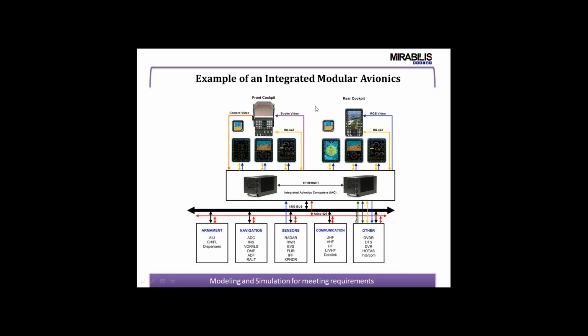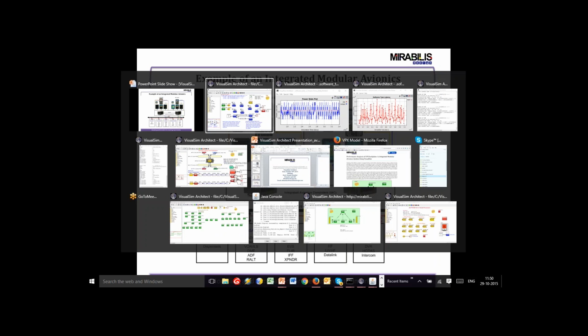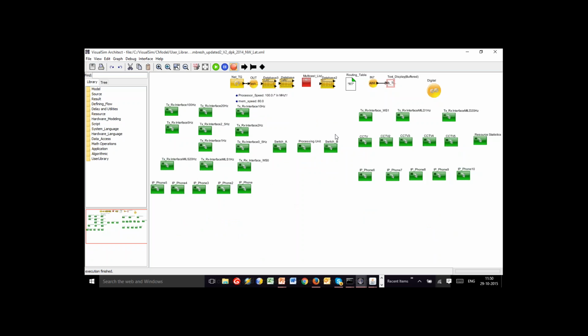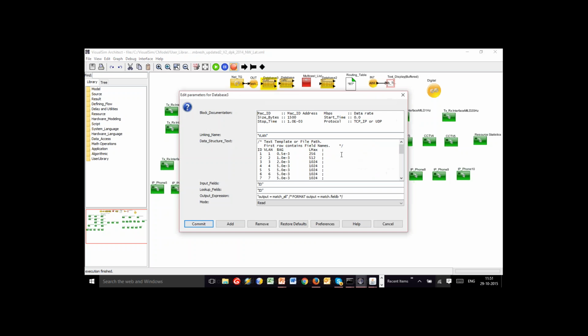At this point, I'm going to go over and show you a very active architecture today, which is based on an AFDX based network. So what you have over here is a redundant switch architecture made up of about 30 or 40 different devices that are connected together through this AFDX switch network. It has anything from low rate transmitter receivers at 10 megahertz to CCTVs to IP phones and a variety of other interfaces.